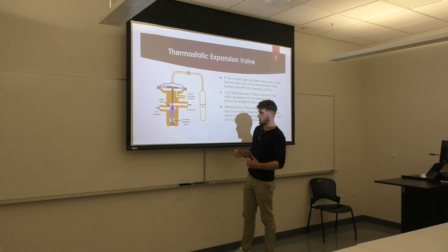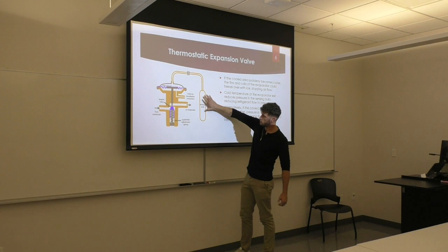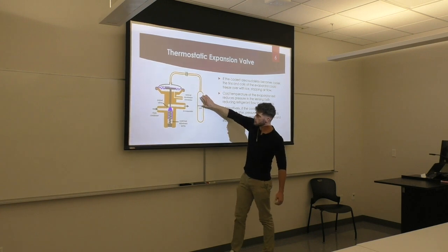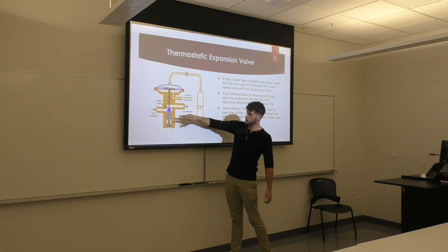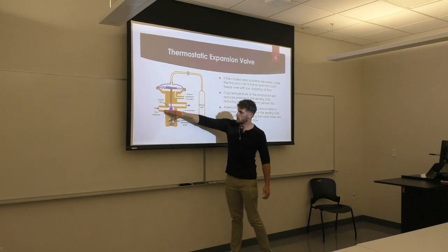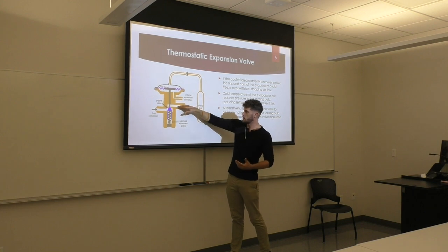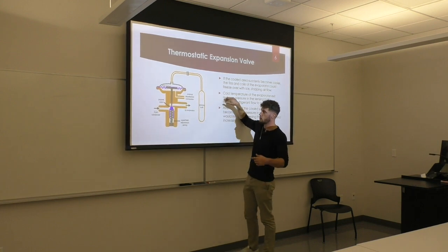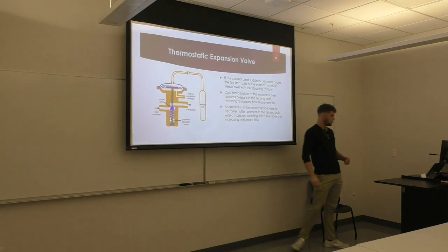And then let's say that your system heated up, like you open the door to your refrigerator and it's getting too hot in there, that increases the pressure on your output, opening the valve, letting in more refrigerant. This is good for efficiency because you're adjusting your flow of refrigerant given the condition, and that's going to turn into adjusting how you run your compressor, using just the energy you need to do what you want to do.